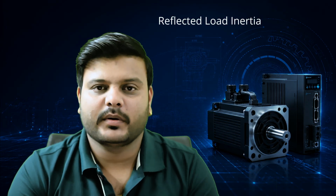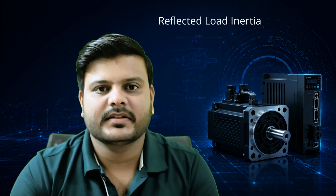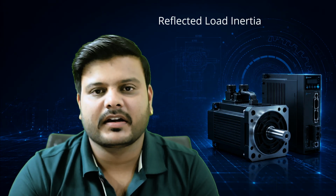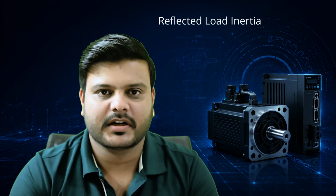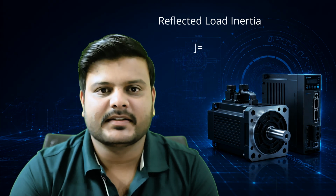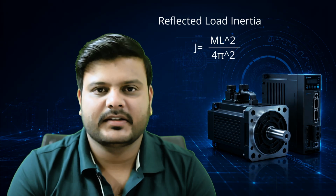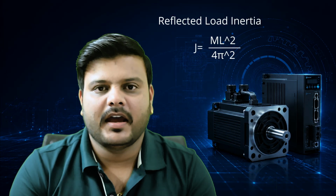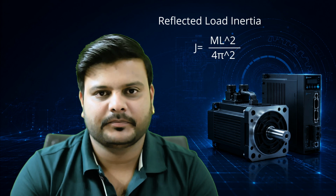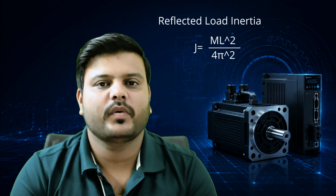Now the next step is to calculate reflected load inertia. The moving mass travels linearly. Since the servo motor rotates, we must convert a linear inertia into an equivalent rotational inertia. We know the formula to calculate reflected load inertia: J is equal to m L square divided by 4 pi square, where J is reflected inertia, m is the moving mass, and L is the ball screw lead. Convert this 10 mm lead into meters, so we get 0.01 meter.